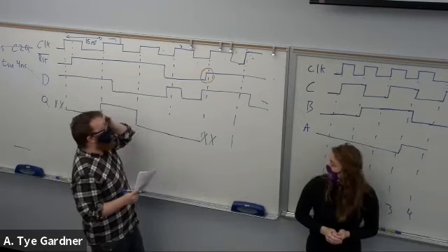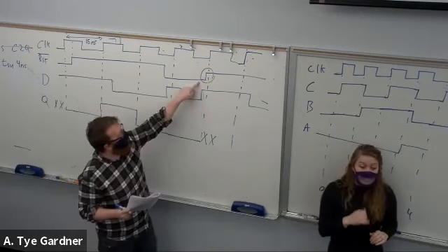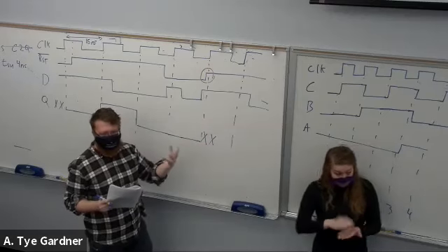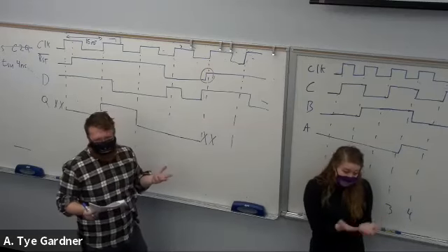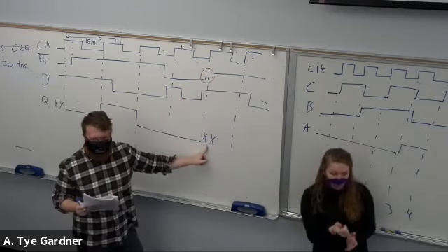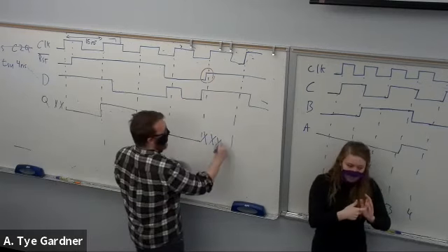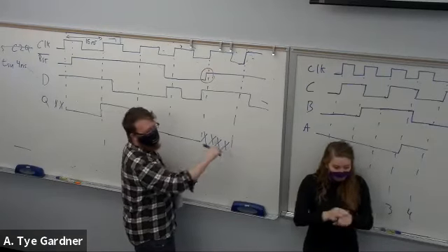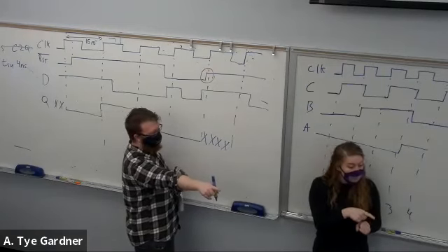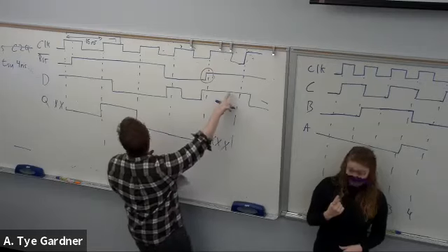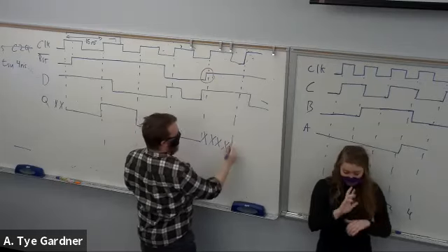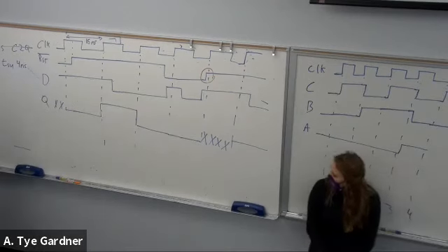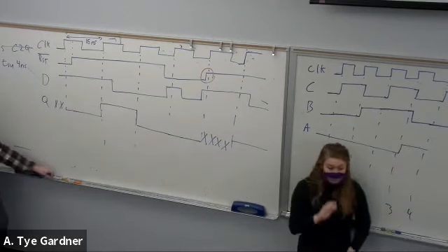Now, if we had kept D at 0 and you wrote 0, you'd probably be right? Almost certainly. But again, maybe not. So if you don't meet timing, we get don't knows. And in fact, we can't know again until another clock, at which point, what do I get? 1. Right, D is 1, not resetting, clock edge, it becomes a 1. Perfect.